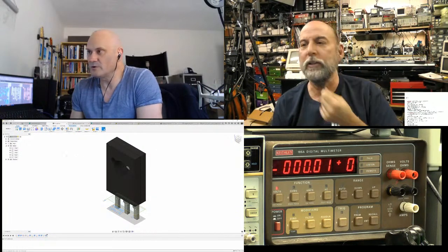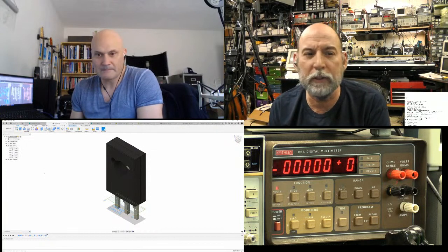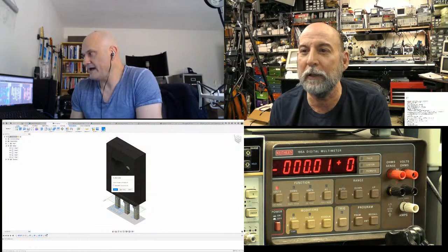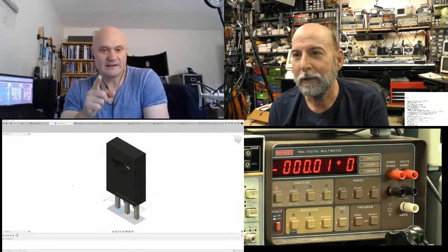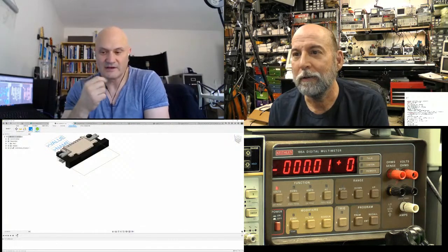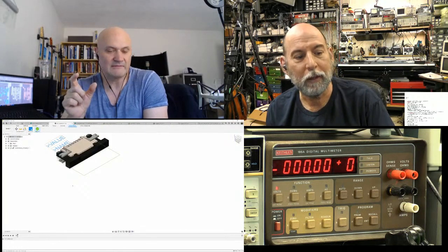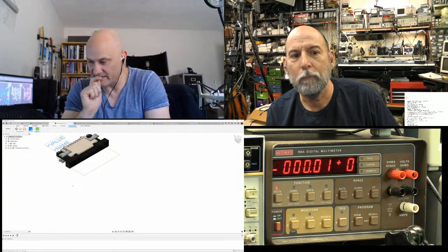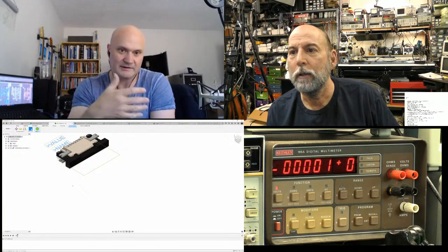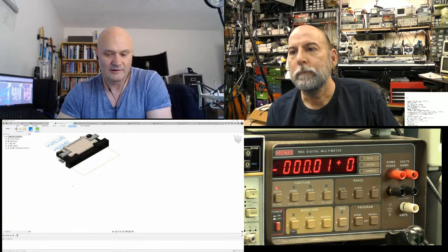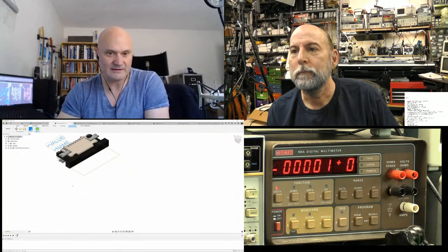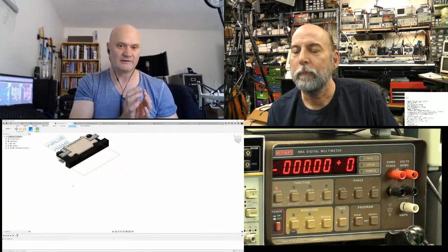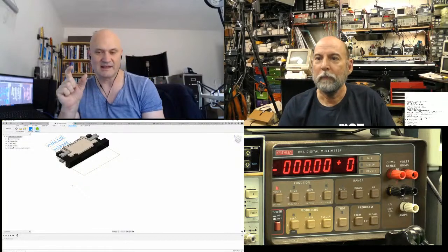It must have been. And somebody mentioned that when you are pulling something from an external library, it's still on you to make sure that it's right. Just because you got it off. Yeah. I got bit in this design because the ESP32 module I used came from, I think, Espressif themselves. They contributed a library to our library on library.io, which is a website where all the community available libraries are. And I copied it into my own library and didn't realize, but they'd changed the layer number.